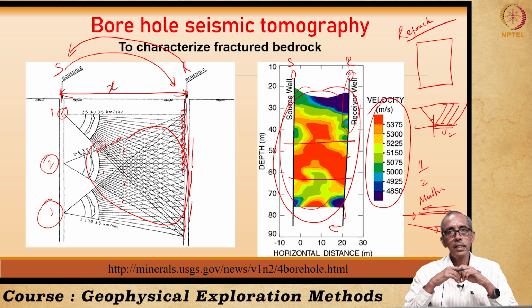Toward the end, we had seen today how we can understand the efficacy of the ground improvement procedure we had followed at the site. Toward the end, we had a look into carrying out survey in the boreholes, which is known as cross hole seismics. So this would have given you some insight on the application of seismic refraction methods.